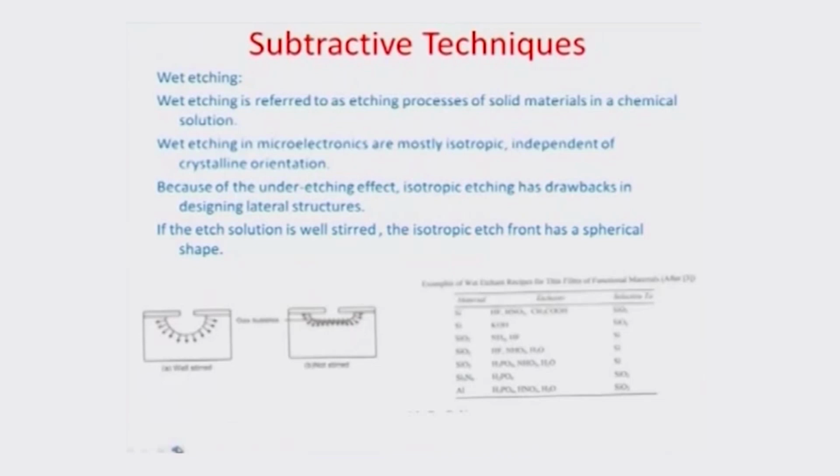So, let us look at isotropic etching. And isotropic etching, really, as I mentioned before, the etchant is able to remove or erode away material at a uniform or homogeneous rate in all the directions. This, for example, is an illustration where there is an etch protective layer, which is now emphasized by the red highlight, the red pen here. And this window here of the etch protective layer gives access to the fluid to go in and start etching away the material which is underneath this protective layer.